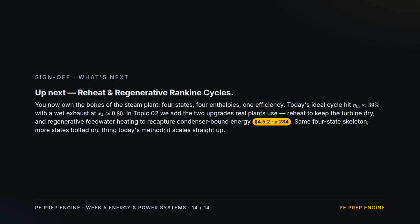4 states, 4 enthalpies, 1 efficiency. Today's ideal cycle hit about 39% with a wet exhaust near 0.80. In topic 2, we add the upgrades real plants use, reheat to keep the turbine dry, and regenerative feed water heating to recapture energy headed for the condenser. Same 4-state skeleton, more states bolted on.